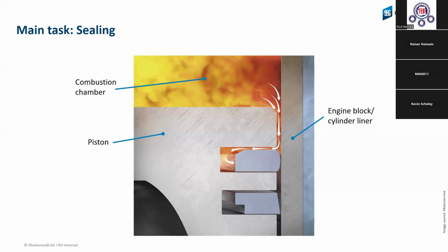Then we have increased blow-by, and also we are not sealing and scraping the oil enough. That means it is better for an engine to have the combustion chamber with a higher load and higher pressure behind the rings. But we cannot drive the engine at high load every time. This is not real life.